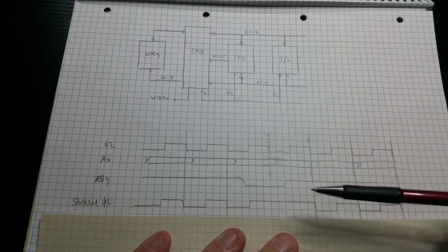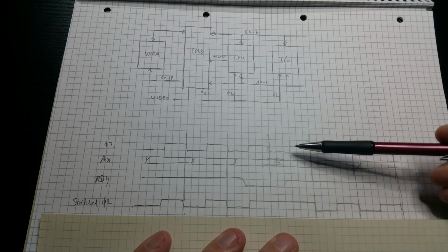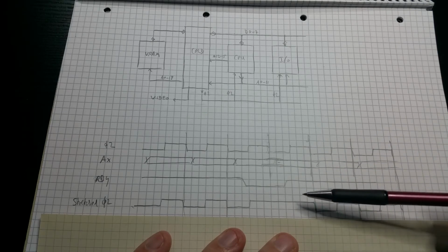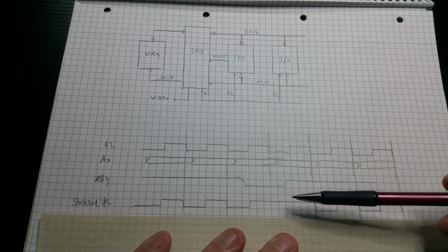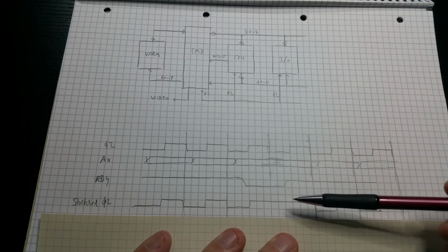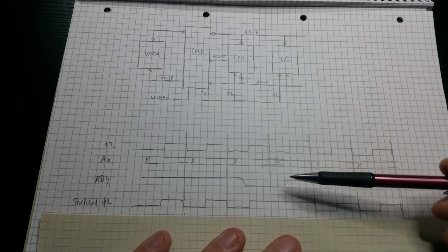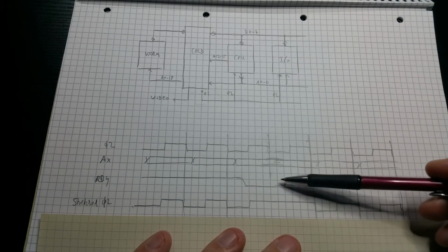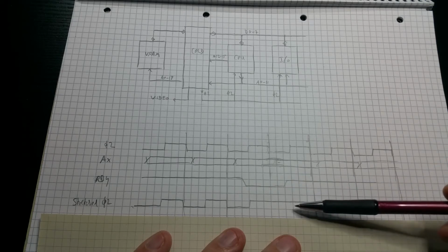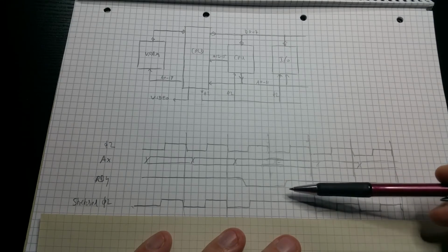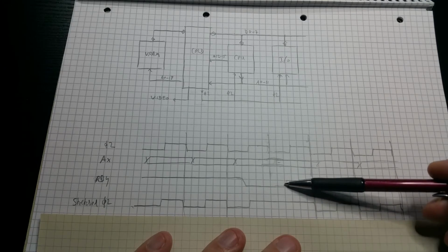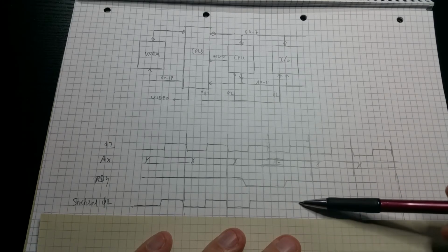In this case, I actually want to have the VIA timers run at full 8 megahertz and use the ready mechanism for that. Unfortunately, it seems there's some kind of problem still in the circuit, which I hope I will eventually iron out. But at the moment, I can only do this clock stretching. There's something wrong with this approach right now. It works well on other systems I built on the original 6502 and so on. So that should actually work, but I have to do it like this right now.